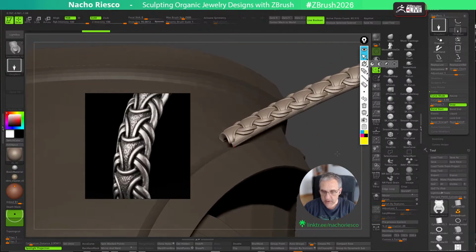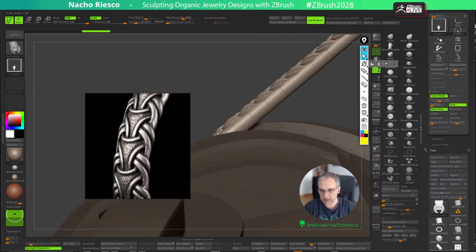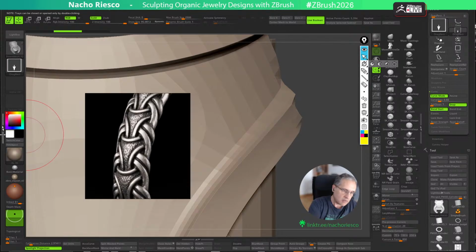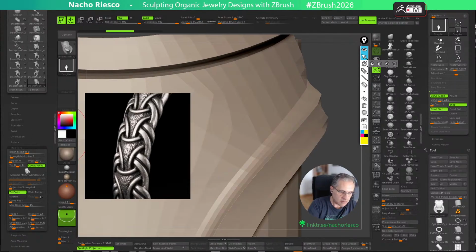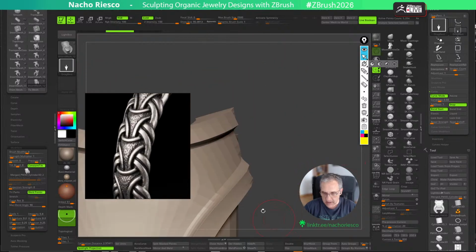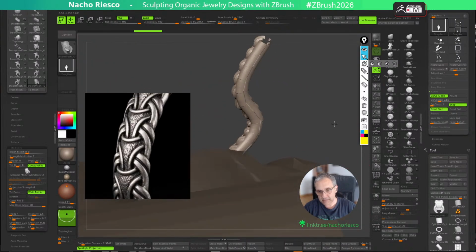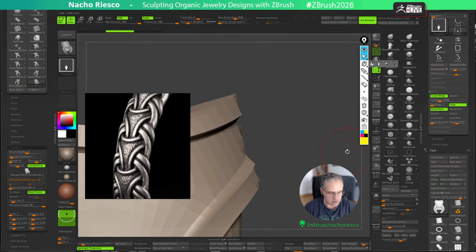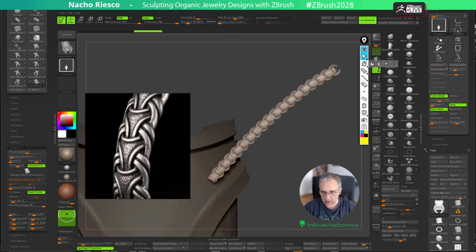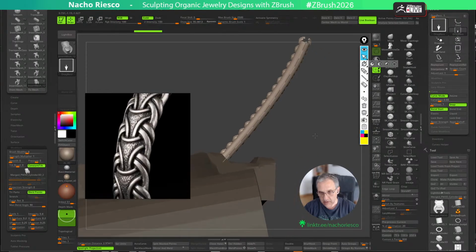So you can see we are almost done, because they are not yet welded, we need to weld points, increase your curve resolution, your maximum bend angle to 90. And now we got it. Yeah, I think it's almost done like this. You can see here.